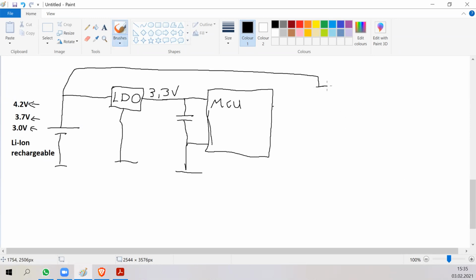Okay, so the simple thing. We can discharge across a resistor and then measure the voltage. Current through the resistor actually. And then is it possible to use it to find the battery voltage? Okay. Yes, you would just connect two resistors. Well, a voltage divider circuit. Yes, exactly. You would use a voltage divider circuit.